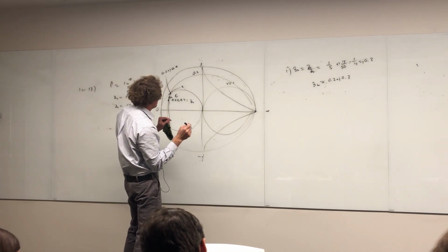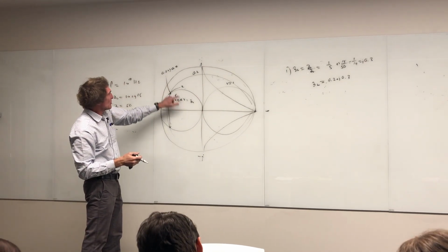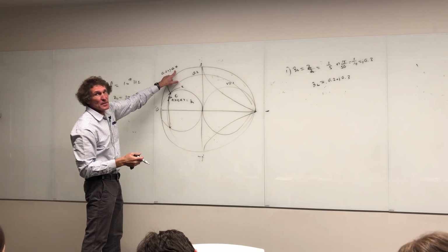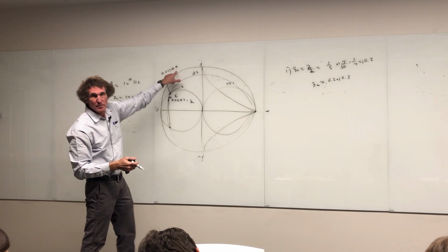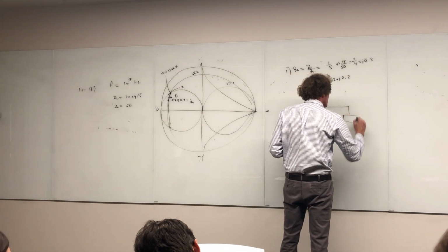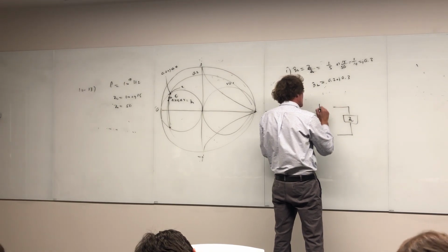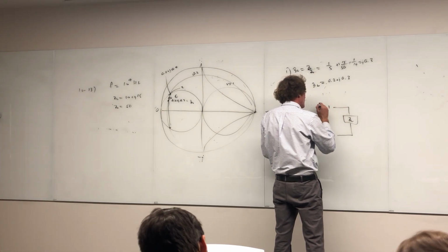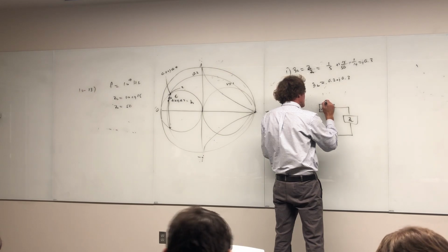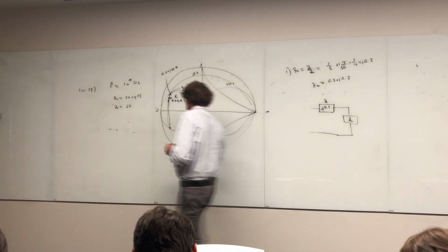Now we're going to add a positive impedance. We were at j0.3, and we're going to go to j0.4, which means we're adding j0.1, correct? So we've got our load over here. Now, our first element is j0.1, and that's an impedance. We'll get to that value in a second.